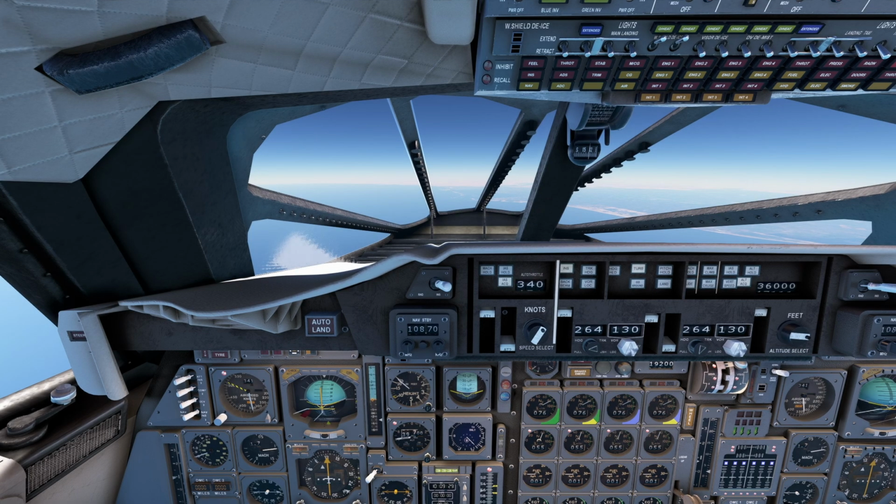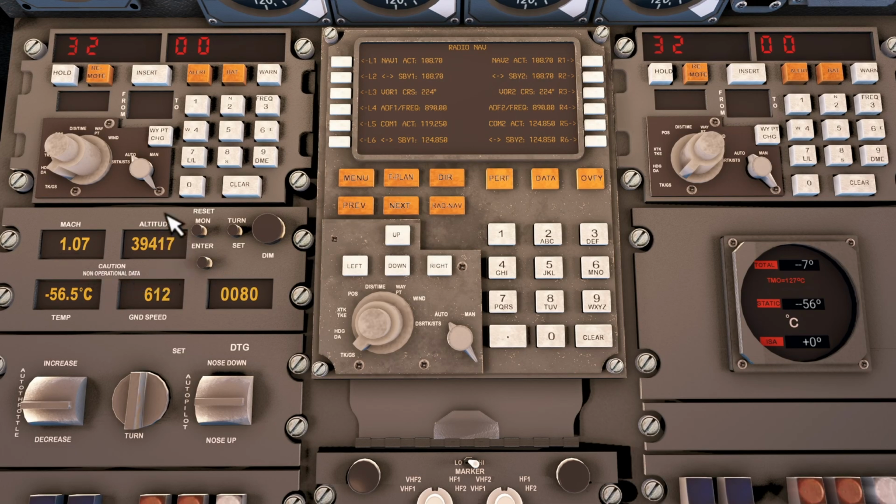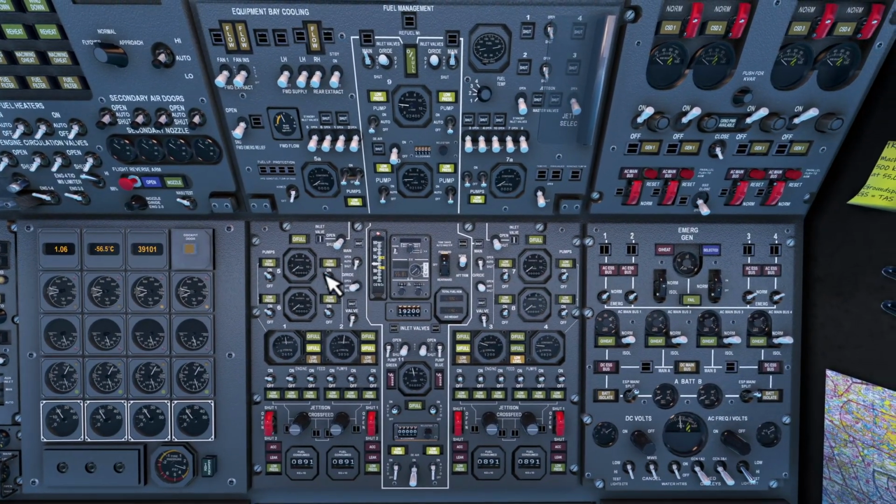We're approaching the normal commercial airliner envelope. We're about to go subsonic, 1.05 Mach at 40,000 feet. That is where commercial airliners usually operate. Our trim situation, still trimming to the front of the airplane. I soon have to stop the trimming because I have not enough fuel on the right side. That's what I'm going to do now.